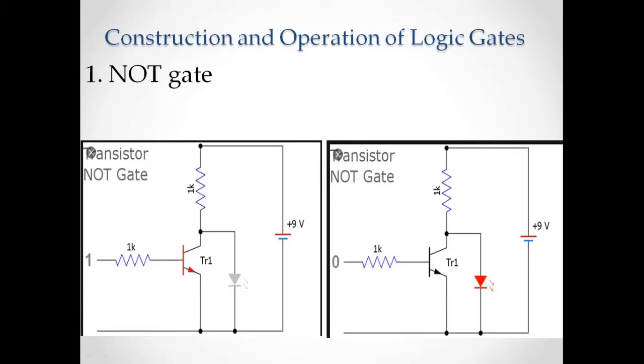As a result, the collector voltage will make a current flow through the collector and the current will flow back to the earth at the emitter, which means the current flows through the transistor and will enter the earth, and no current will flow through the diode which is connected to the collector, because current always chooses the less resistive path. Here the less resistive path is through the transistor. So there is no glow of the LED at the output, which means you don't have an output.